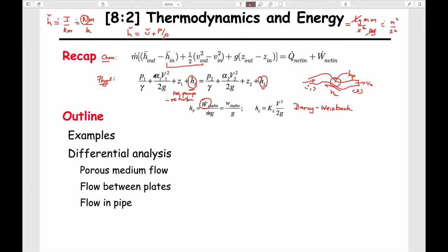And again, it's important in writing this equation that this is a mass flow rate, which is a scalar value and always positive, kilograms per second, and that this is between the upstream and the downstream. It only works if that's the case. The heat energy that's put into the system is positive if you're putting energy into the system, burning something as in a jet engine, and it's positive if you're putting work into the system, as in pumping something. And so those are the sign conventions that we have to deal with. But I think hopefully you can see the parallels between these two. They're really the same equation. All they are is written differently to include enthalpy in this particular case, to include the internal energy that you might want to put into the system. Okay? All right.